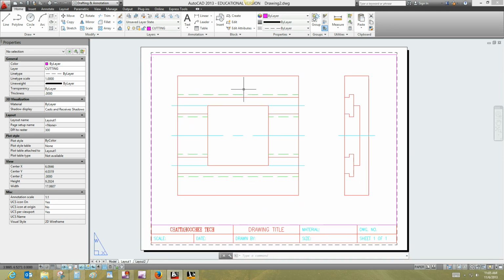Okay, so I may have introduced polylines in previous videos, but I'm going to use it again because polylines. Poly means many lines. Okay, it connects many lines together, but more important than that is you can assign properties to polylines that you cannot assign to regular line types.